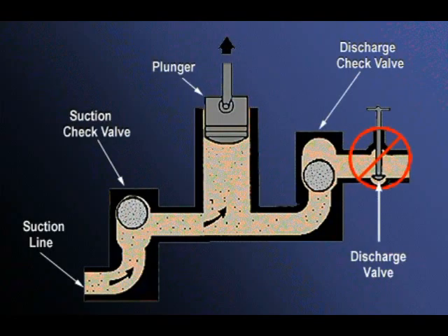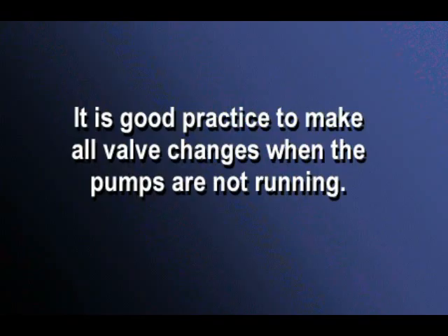As mentioned earlier, an important operational aspect of any positive displacement pump is the proper control of valving when the pump is operating. All equipment operators must be thoroughly familiar with the valving arrangement so that no discharge valve is closed before another valve is opened. This point is extremely important since considerable damage can result if the pump works against a closed isolation valve, even for a short time. It is a good idea to make all changes in valve settings with the pump shut